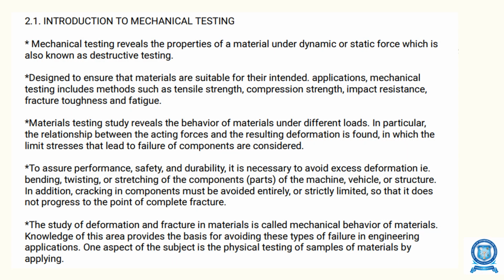So mechanical testing is nothing but the material will be under dynamic and static force. I mean, we will be giving dynamic and static force constantly to the material and checking the quality of the material. Those kinds of testing we call mechanical testing. It is also called destructive testing. Once we do the mechanical testing on the material, we can't reuse the material. So not like NDT.